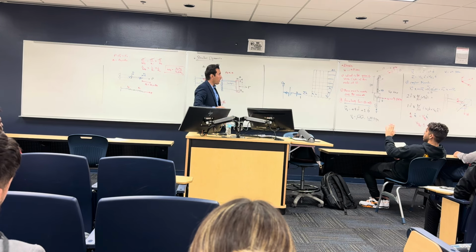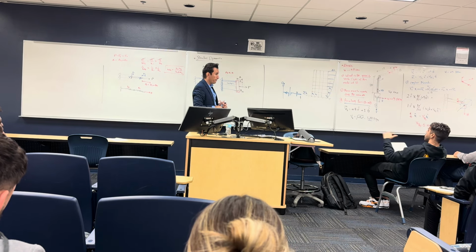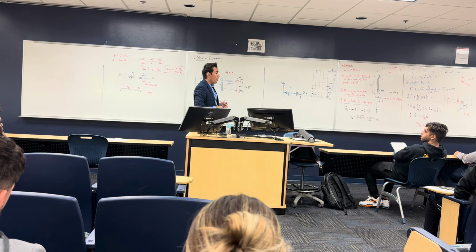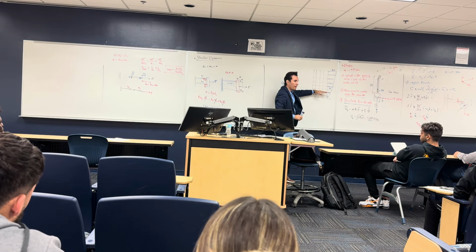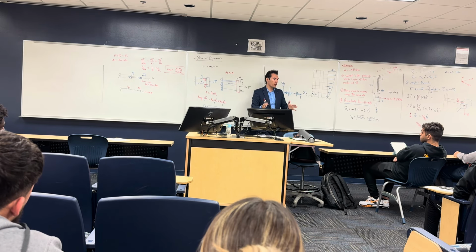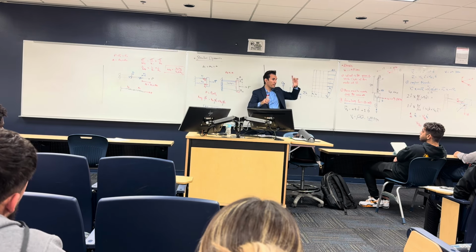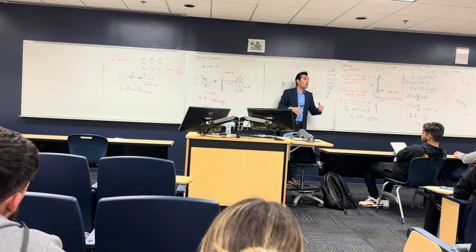So does that mean, since the force is going to be different in each beam, the more beams we add, the more the force gets distributed? Well, the beams add more stiffness to the slab, so it's going to make the slab more rigid, because the slab is not perfectly rigid. As you increase the thickness of the slab, it's going to be more rigid. That's why we ask whether the slab is a rigid or flexible diaphragm.